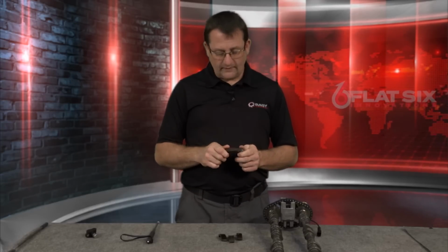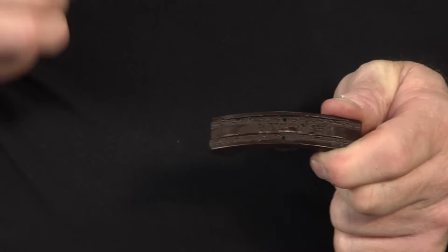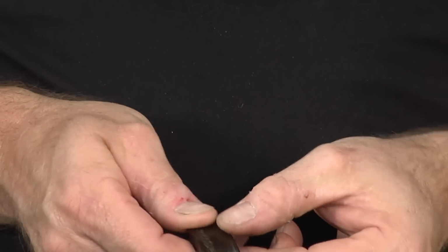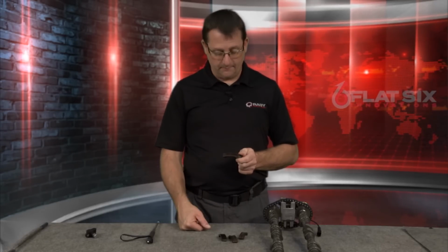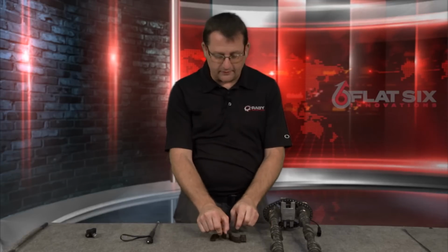How is that possible at this mileage point? This engine shouldn't have any wear on it. I said, well, if I pull these wear guides out and they're not worn at least as bad as this one is, a good example, I'll do the job for free. If not, you pay me full price. He accepted my deal, and when I pulled them apart, they were worn worse than this one by far, and it proved my point. Put it back together, my deviations were well within 2 degrees at worst. Most of the time they were like 3/4 of a degree, which is very good, and we were able to do the rest of the preventative work.